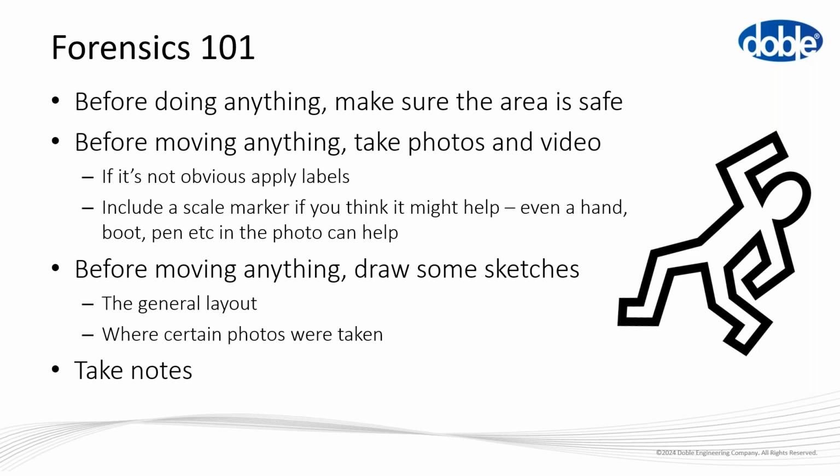And obviously, number one, when you get to site, please make sure that the area is safe. If it's a cable, particularly an XLP cable, there could be a lot of stored charge in there. So please make sure everything is earthed down safely before you do anything. If it's an oil-filled asset, think about safety, think about slipping, think about the fact that it may have PCB in it if it's a very old asset. But please make sure everything is safe before you do anything.